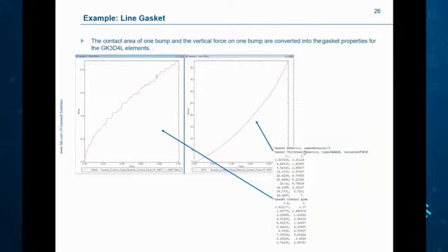So how would I get my gasket properties? Well, one thing I could do is test the gasket and push it down in a test machine and extract pressure and closure curves, and that's actually done by some users. I don't have a test machine, so what I did was a plane strain simulation.